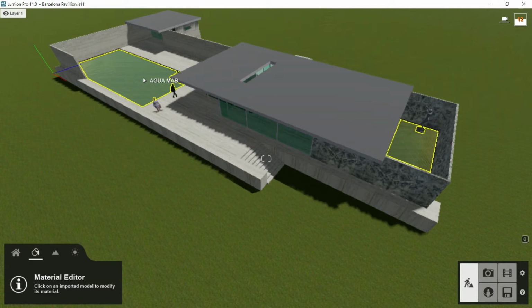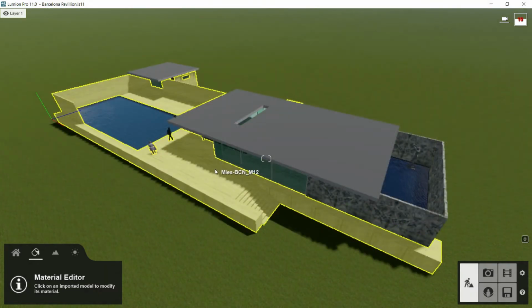So it is very important that before coming to Lumion, you worked your model in SketchUp and you applied there different materials or even colors just to distinguish all of them very easily here in Lumion. In any case, you have to know that our SketchUp file is linked with our Lumion file. So if we need to change something in our SketchUp file, we can do it, and then when we save it and we reload here in Lumion our file, those changes will appear. We will learn how to do that in a specific exercise for applying materials in all the pavilion.